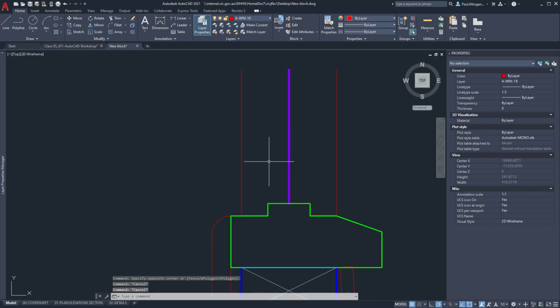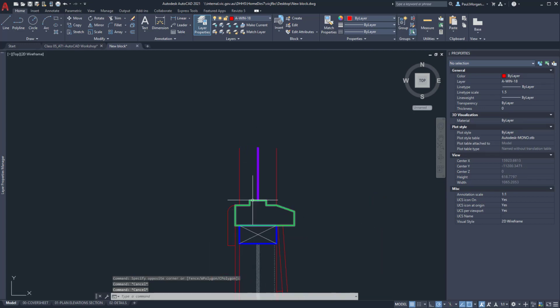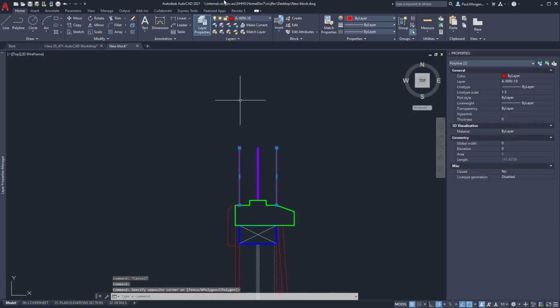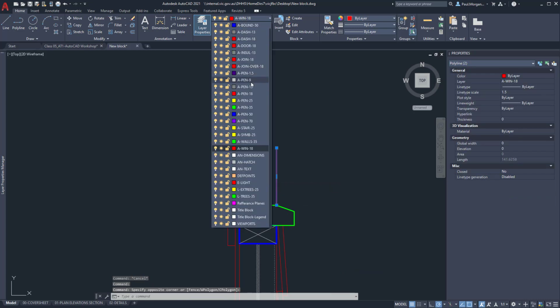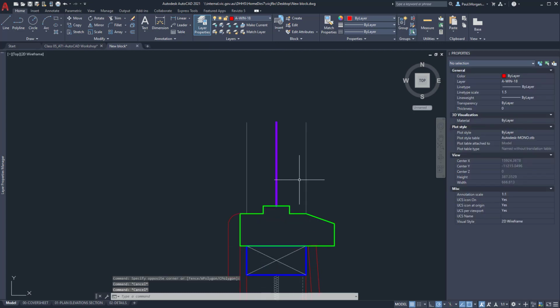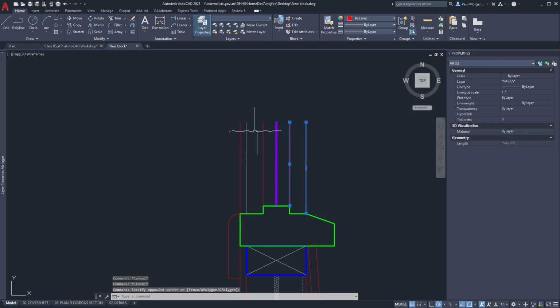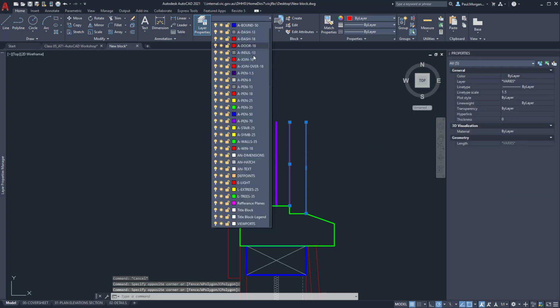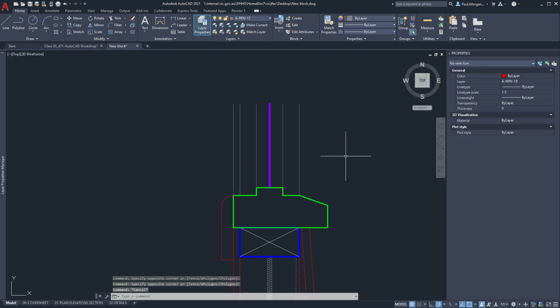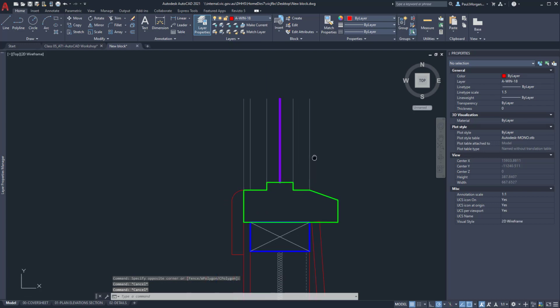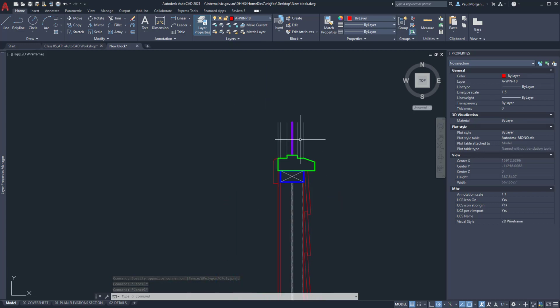Now I'm playing around a little bit with line weights. I'm not sure what works and what doesn't. But a couple other things I need to do now is I'm going to make these line weights lighter. I'm going to make these 0.13. Okay. And I'm going to draw another few lines. And same there. And I'm going to make all of these 0.13. And the reason for that is because they are further back in the distance. They're in projection and they're on the other side of the window that we're not cutting.